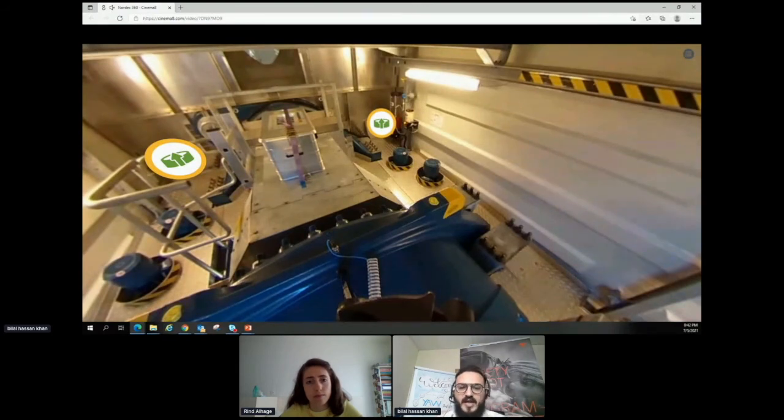the location. Like if I talk about Pakistan, in Pakistan we have too much dust, and due to dust, our filters and other components start to heat up very early, so we have to perform the maintenance twice a year. But in some other countries where we don't have too much dust and other factors like temperature, we only perform the maintenance once a year.